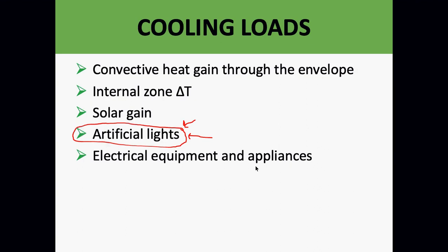You're right that an oversized air conditioner, you would think, would dehumidify better. The problem is, by the time it dehumidified, everyone in the space would be way too cold. Make sense? Yeah. Okay.